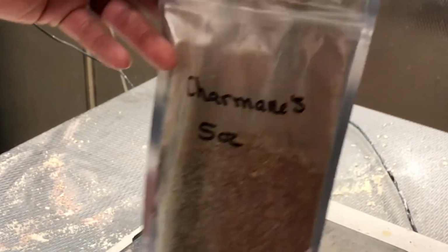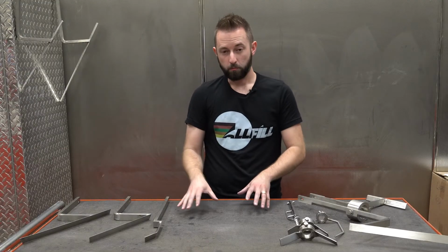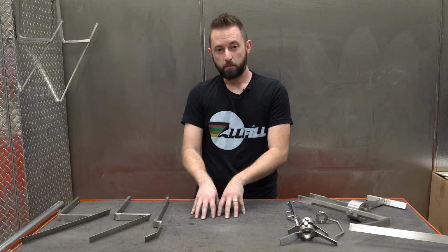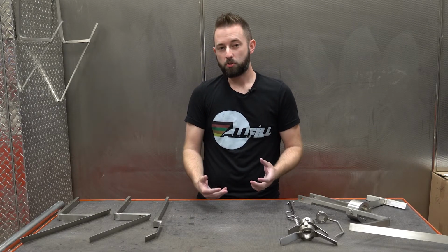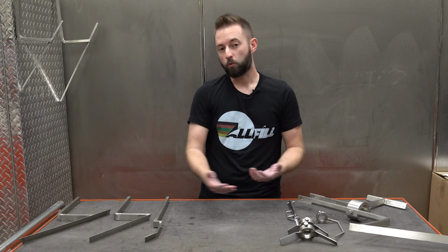So typically what we'll do is we'll configure one of these agitation blades with a 20 RPM speed with no off delay. So it's as minimal agitation as possible to help alleviate the issues with degradation and/or a separation of your mix of product.